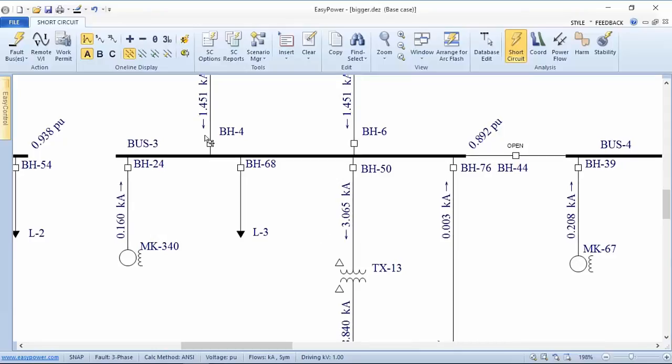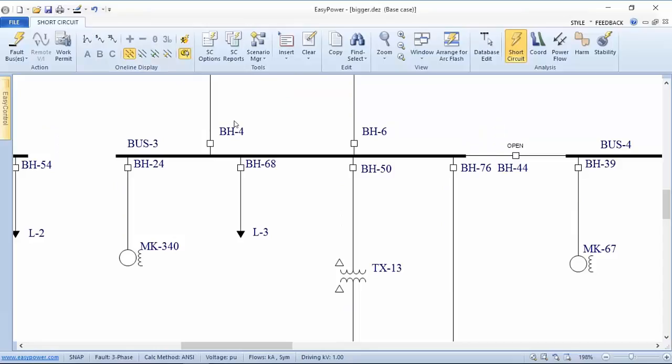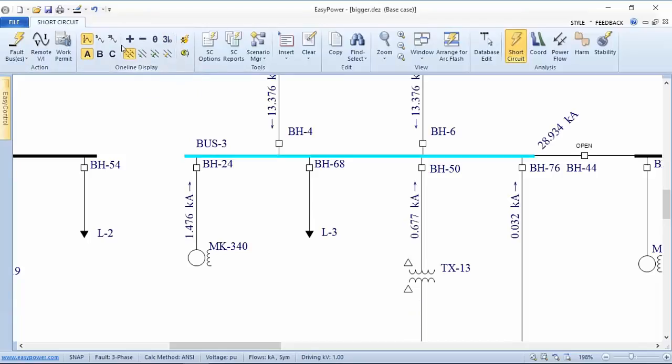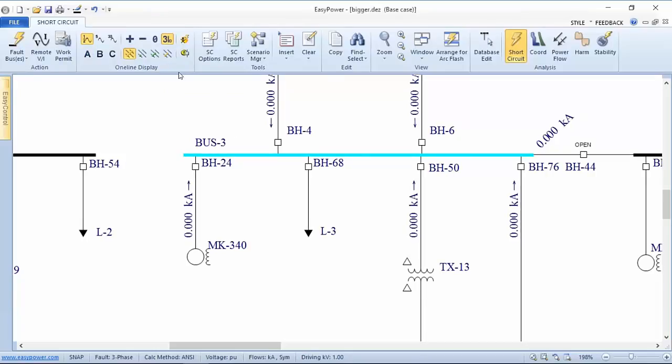And so the tool does that automatically in a feature that's called Smart Duty, and it's an extension of the equipment duty display that we talked about earlier. All right, so that was the time difference, the sequential representation. I guess the last thing I wanted to touch on was actually the three times zero sequence current for a fault in a particular location. The tool will also give us the 3 times the zero sequence current for a display, and in this case we want to have a single line to ground.